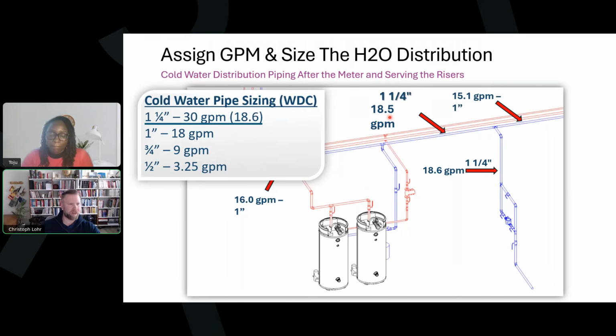I would think we get questions about that. It's not at random. It's actually very intentional, but it does go through different phases. But that's one of the things that you do want to look at: thinking about, again, that segment of pipe, what is downstream of it? And if it is upstream of the cold water makeup to a water heater, you do want to include hot water fixtures on that line.